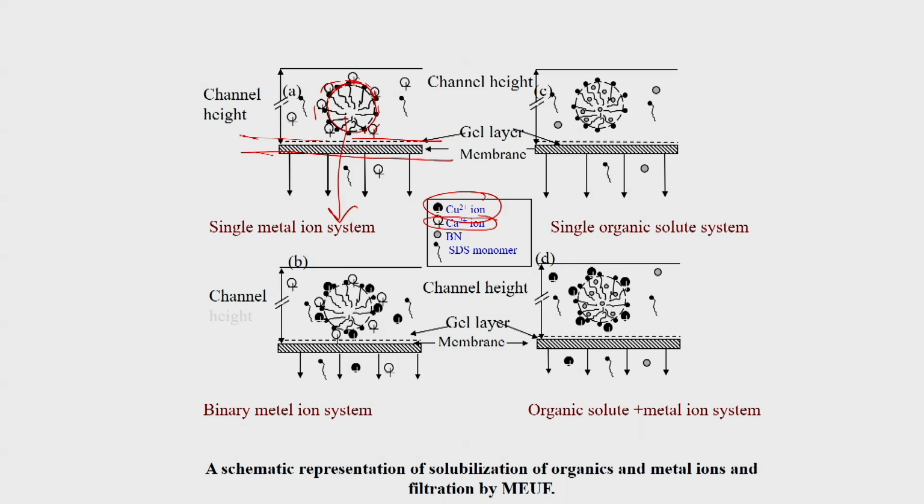But we told earlier that above CMC some monomers will be there in the surfactant solution. So, these will pass through the membrane along with a small amount of the feed solutes. Whenever we have different organic compounds like beta naphthol, these will be trapped inside these globules, and after this membrane separation process some monomers, which are not trapped by the micelles, will come out in the permeate.